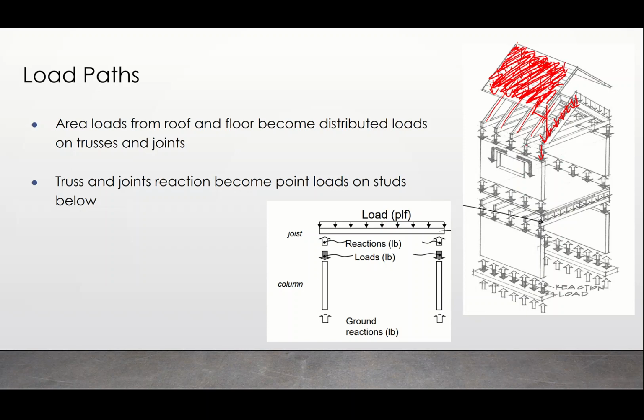Then we're going to go to the bearing wall, and those joists are evenly distributed over that bearing wall. So that's what we got. It'll move straight through. We need some arching around this window here. So the ones on the outside might be a little bit more, but still uniform. And then we're going from joist to bearing wall to ground again. So understanding that route, understanding pounds per linear foot. So getting from area load to distributed load we will talk about, but that is ultimately the goal. How do we make something from a distributed load and carry that throughout?